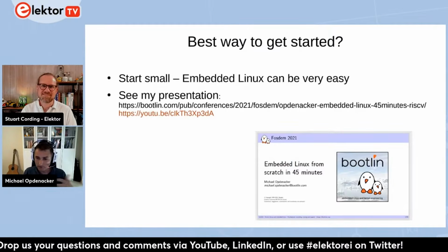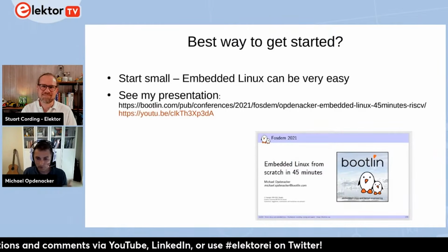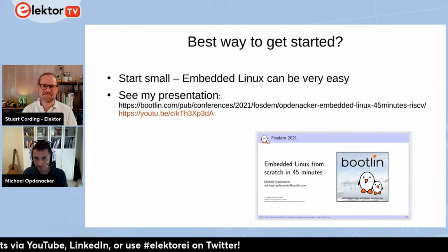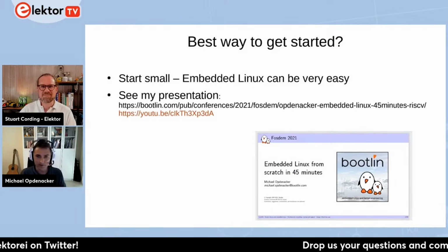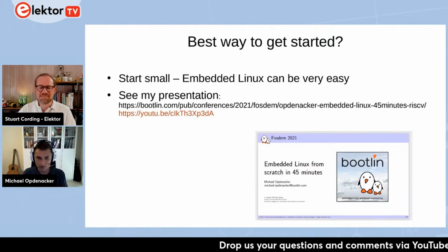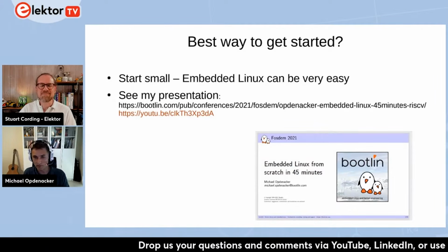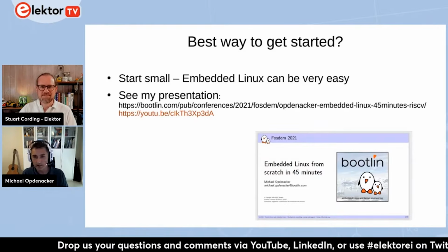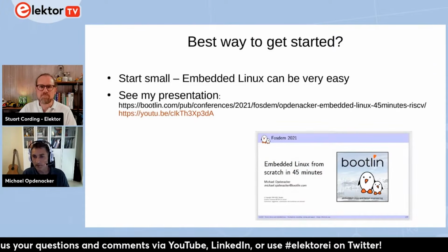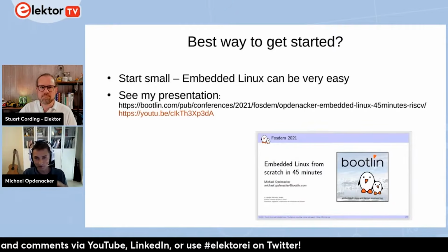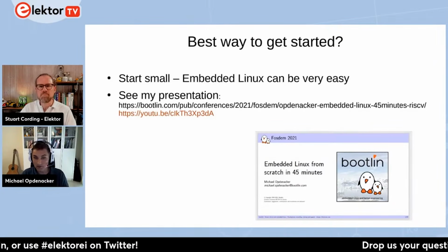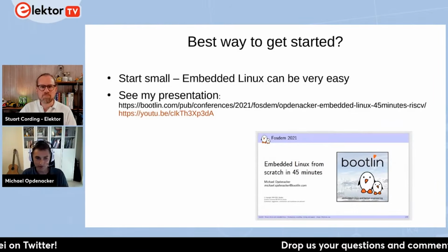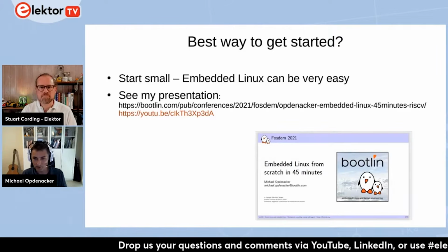Then just compile a bootloader and kernel for this emulated architecture, and just flash a simple file system with BusyBox. So just simple command line utilities that are super easy to compile. Just flash them on a drive and boot your device with that. And then you can see how simple things are. And then you can grow in complexity and add more things. But Linux can be super simple. You just need 3 components: the bootloader, the kernel, and BusyBox. That's a user space program.